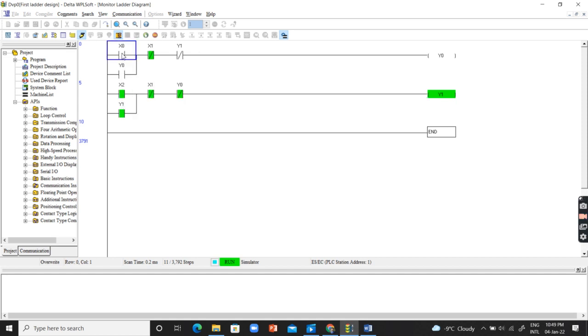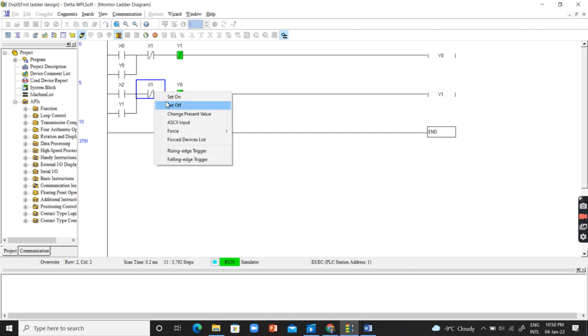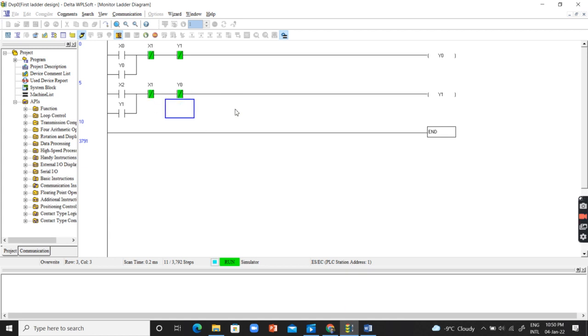And now if you try by mistake to push the clockwise button, it won't work. You can see that it won't turn the output on. The motor will keep rotating in anti-clockwise direction. So again, if you want to turn it in the other mode, you first need to disconnect this power button, right? And then reset it again and then do whatever you want.